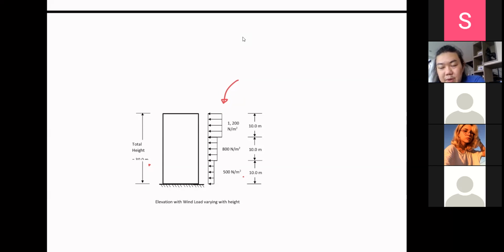If your building is on open terrain, the wind is going to be different from a building in a metropolitan area like Bangkok. They're going to be different, as is the shape of the building. So with this, now you can calculate, because you know that the tributary width is how much? 6 meters, right?